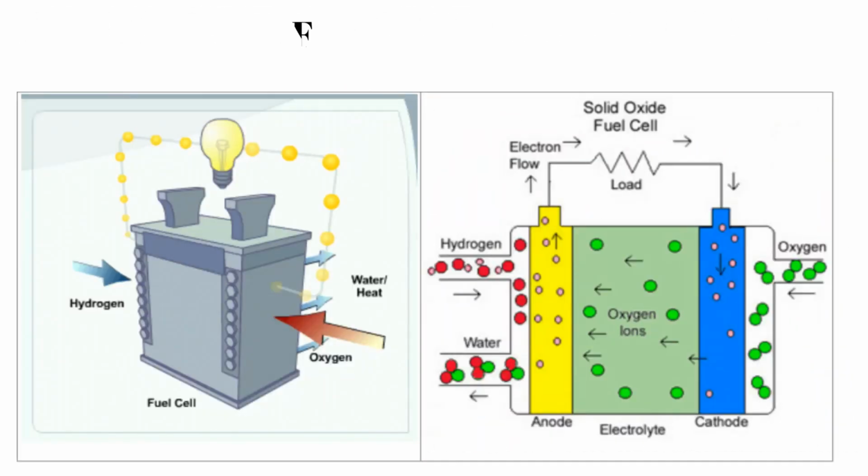One common failure in fuel cell systems is the internal failure of the air compressor. The air compressor is a critical component in the air supply subsystem, responsible for delivering the necessary airflow to the fuel cells. Air is required for the chemical reaction with hydrogen to generate electricity, and any fluctuation or interruption in the air supply can severely affect the efficiency and output of the fuel cell system.